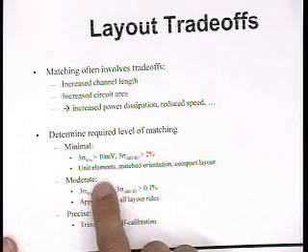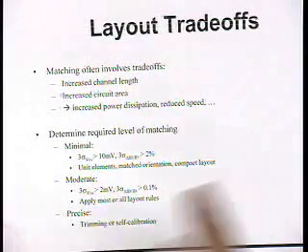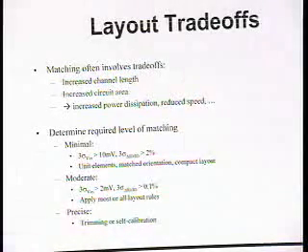In the beginning of class, we talked about if you have a W over L of 100, and you're trying to match it to another W over L of 100, it's better to actually use unit elements and intermingle them. And we'll talk about that a little bit more later. That'll get you down to this level, 3 sigma, 10 millivolts, 2%.